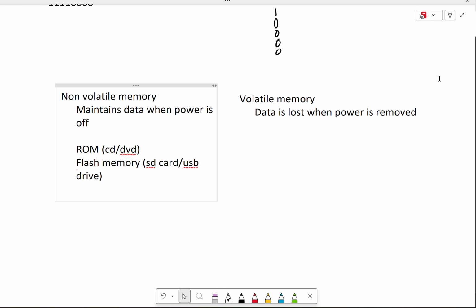Flash memory is probably more along the lines of what we would call electronically erasable, programmable read-only memory, or EEPROM. Okay. Now, if you think about it, EEPROM, or the flash memory that's on a controller, that is what we were just talking about, where if you're going to write your trim files and your engine parameters or your transmission shift calibration points, that kind of stuff, that's stored in the EEPROM, or the flash memory part of a controller.